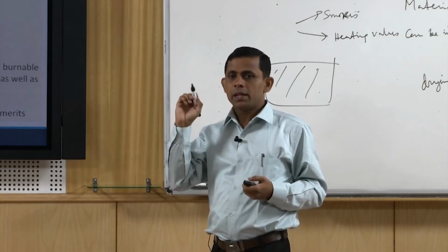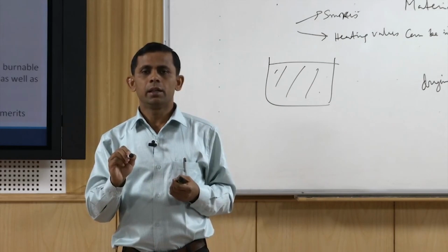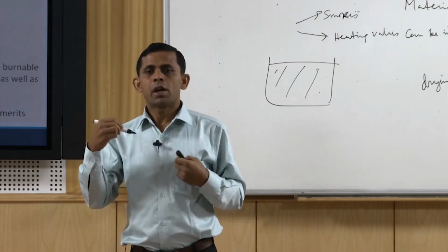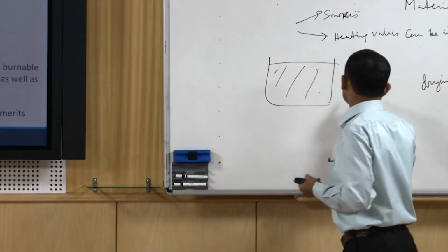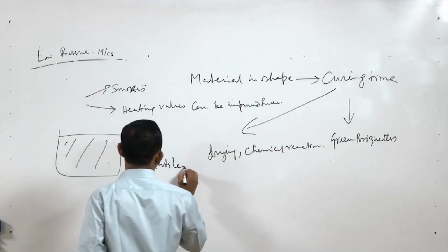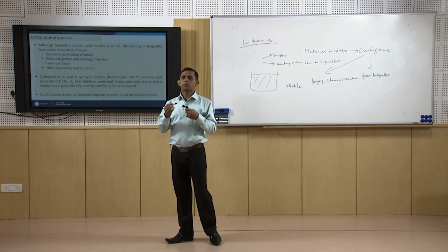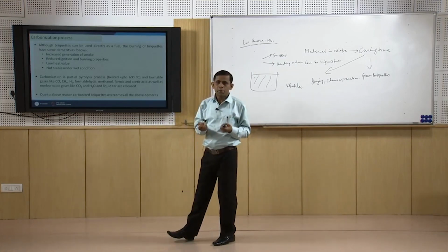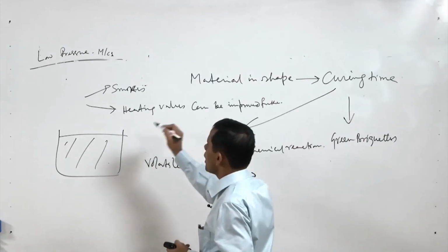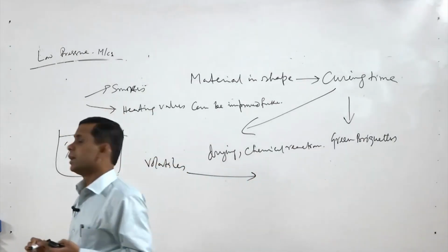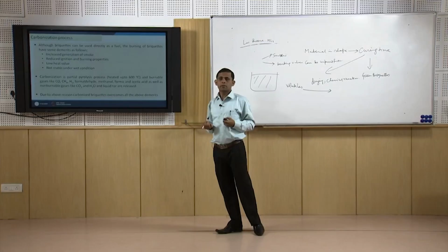As you have seen in the pyrolysis module, carbonization improves the carbon content in the material, gives higher heating value, and removes the volatiles. So, carbonization of the briquettes will also help us to make them more carbonaceous and to reduce their volume, and the volatiles produced during the production of carbonized briquettes can be used for the heating required for the carbonization process.